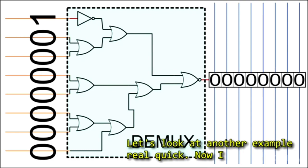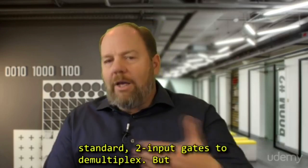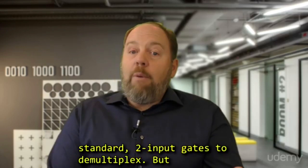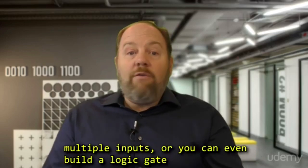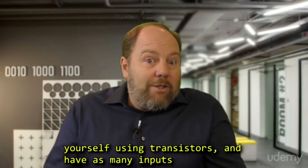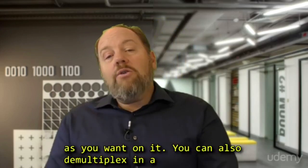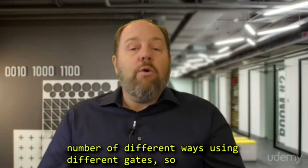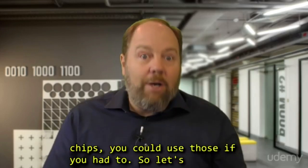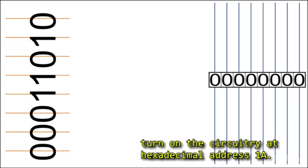Let's look at another example real quick. Now I wanted to show you an example using the common standard 2-input gates to demultiplex. But remember, you can get logic gates that have multiple inputs, or you can even build a logic gate yourself using transistors and have as many inputs on it as you want. You can also demultiplex in a number of different ways using different gates. So if you happen to have a whole mess of AND gate chips, you could use those if you had to. So let's turn on the circuitry at hexadecimal address 1A.